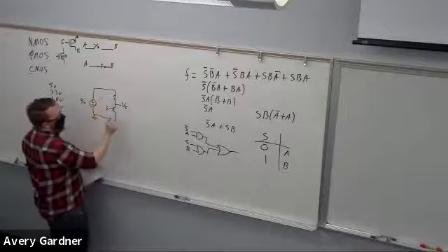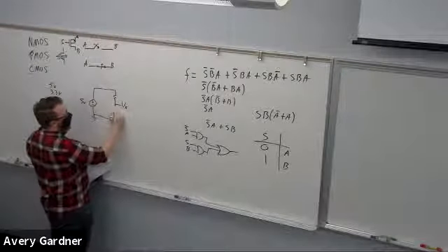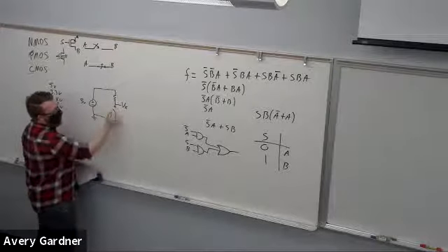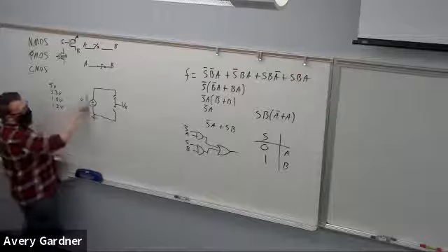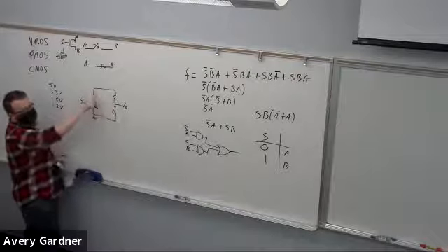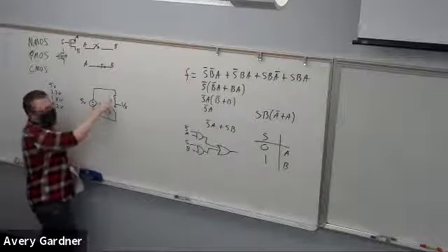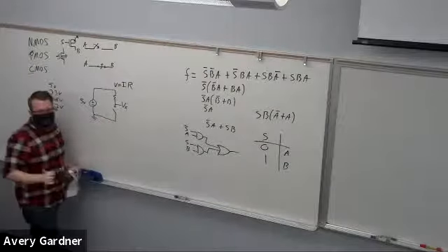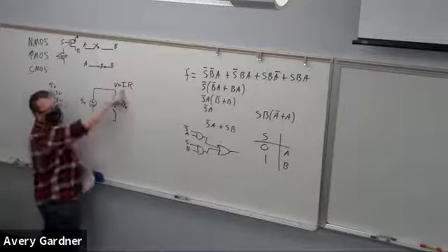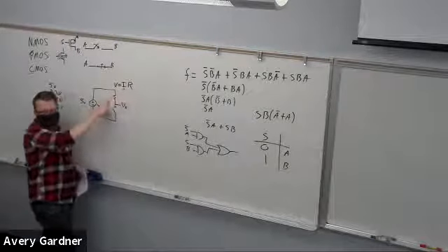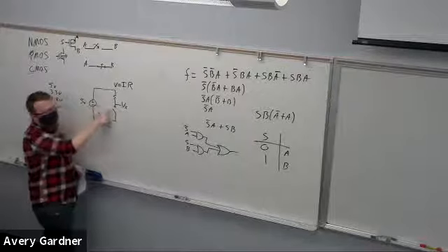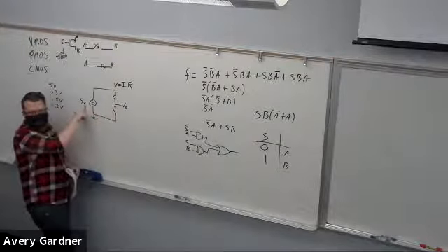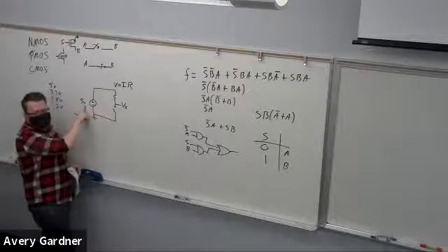Okay, let me draw this real quick. Open switch, right? 5 volts just sits and hangs out here. The voltage drop over the resistor, Ohm's law, is V equals IR. If current is 0, the voltage drop is 0. The current has to be 0 if there's nowhere for it to flow. Therefore, Vx is the same as 5 volts, therefore on.